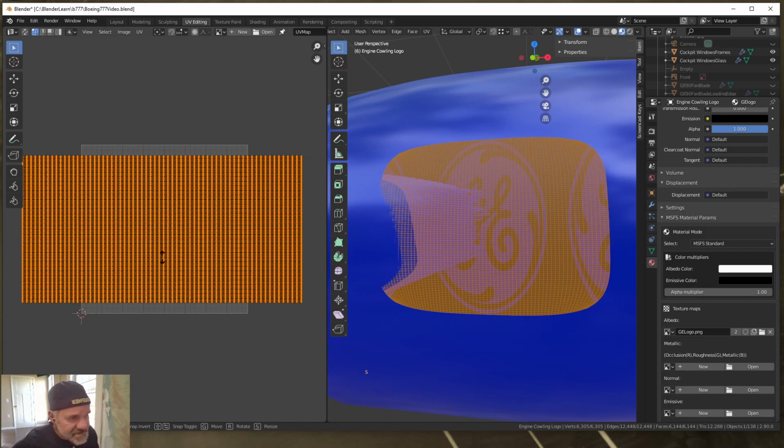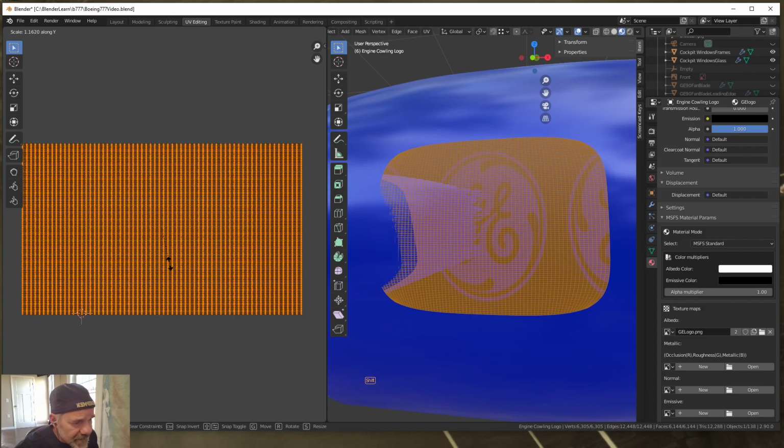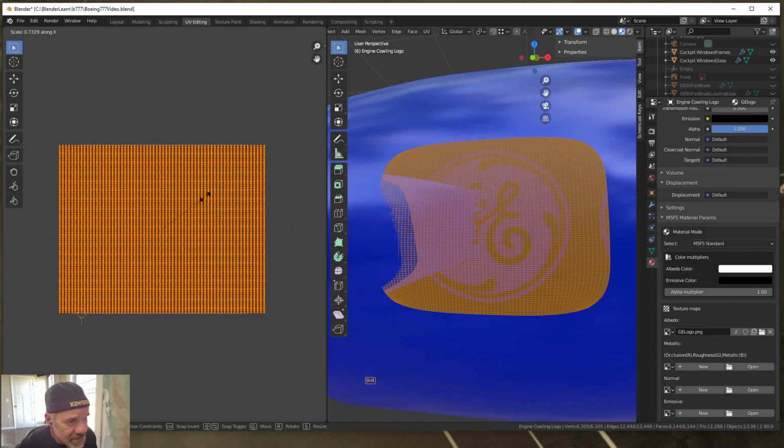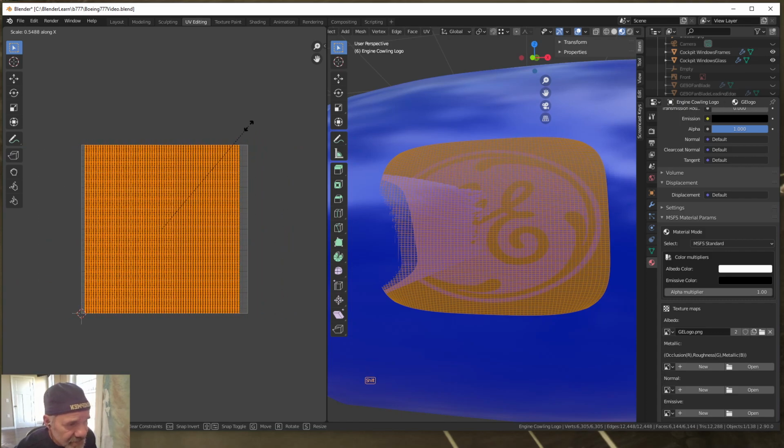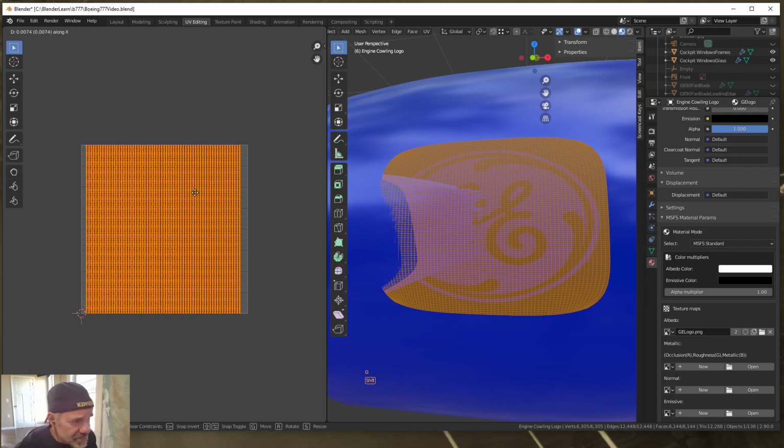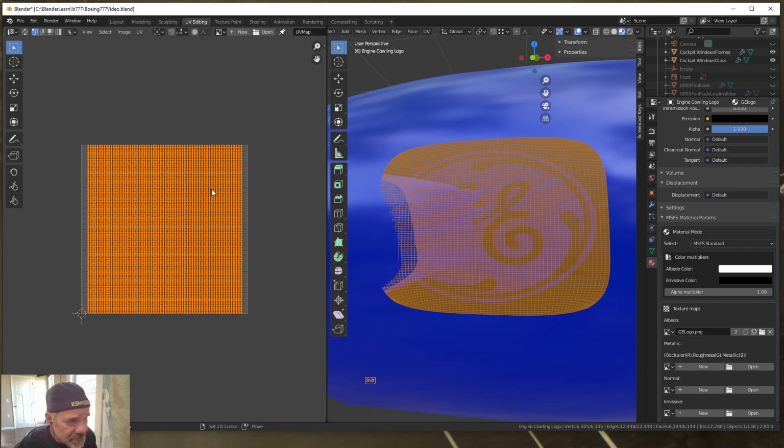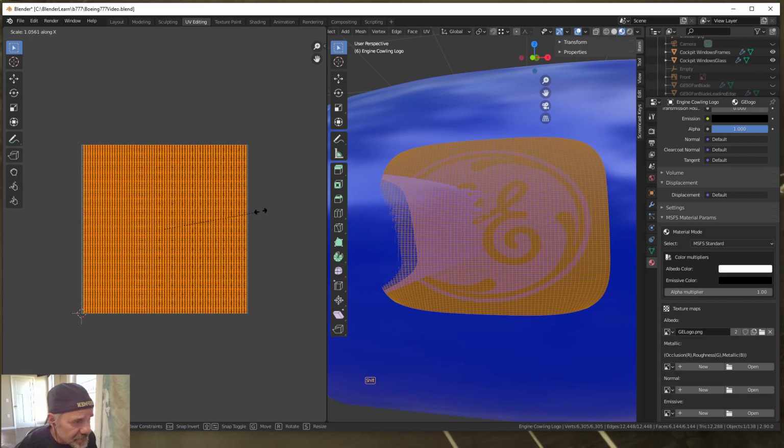All right, so let's scale this in the Y. Bring those polygons up. Now, I'm not going to get this perfect for this video, but I just want you to get the idea. So we're inside the box in the Y-axis. Now I need to scale it in the X-axis. And I'm holding my Shift key to fine-tune my mouse movement. I'm going to move this in the X direction now and get it right there. And then I'm going to scale it one more time so we're pretty close here.